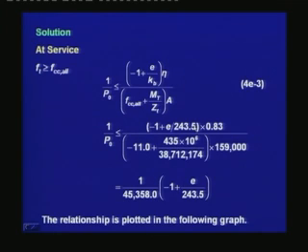Once we substitute the variables, the values of Kb, eta, the compressive stress at service which is 11 Newton per millimeter square, values of the total moment which is 435 kilonewton meter, and values of Zt and A, we find the inequality relationship which is 1 by P0 has to be less than or equal to 1 divided by 45358.0 within bracket minus 1 plus e divided by 243.5.